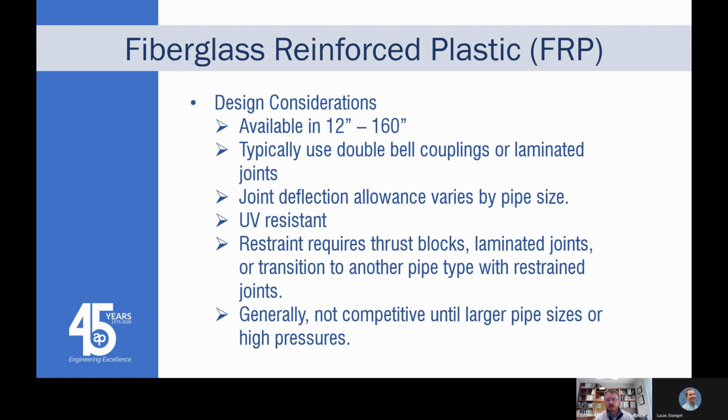So just to put a plug in here, Lucas just did a big project for an irrigation district over in Umatilla County. How big was that pipe, Lucas? So yeah, it's like a 7-mile long pipeline, and half of it was 72-inch diameter and half of it was 75-inch diameter. And we bid options for steel and FRP, and sometimes it kind of depends on the market. We were actually assuming that the steel was going to come in lower, but the fiberglass came in lower, and so that's what we ended up doing. But it had a combination of steel and fiberglass.